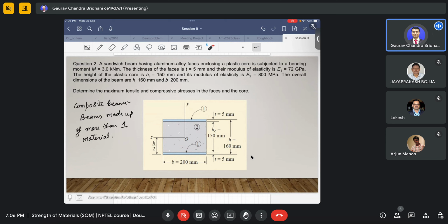It can resist the shear, but it is not able to take a higher amount of tension, basically the bending. It is not able to take more bending. So what we do is reinforce it by putting some plates or sections of other materials which are of high strength.